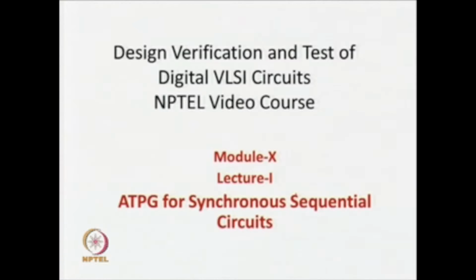So, in the new module 10, we will mainly look at how the same technologies, like stuck-at fault models, collapsing, and ATPG algorithms, whatever we have seen for combinational circuits, map to sequential circuits. So, today we learn about automatic test pattern generation for synchronous sequential circuits. You should know that sequential circuits can be synchronous as well as asynchronous, which we learned in our basic digital days, but here we will mainly deal with synchronous sequential circuits with a single